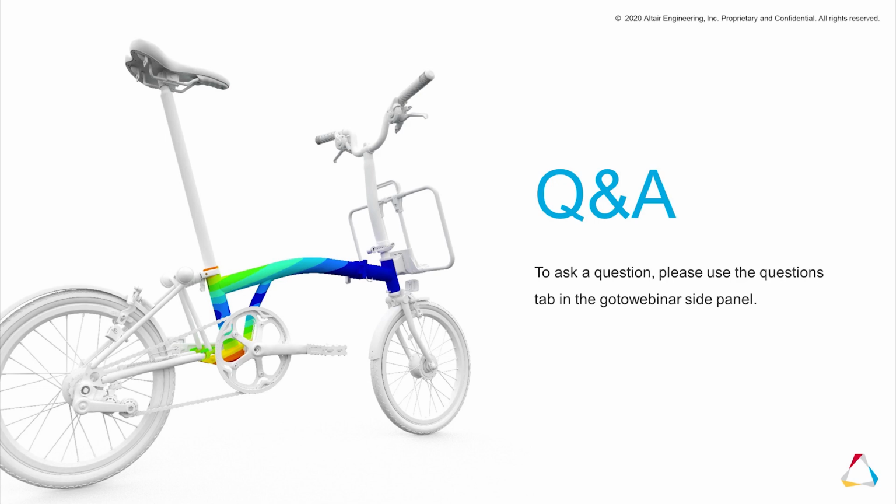Do the geometry import settings have a big influence on the results? In SimSolid, we bring in solids and the surface faces, but then we create facets on the face. The reason we bring in a faceted surface is efficiency. It makes it more lightweight than having to bring in a heavy surface and solid model. The rule of thumb is you just need the facets to be visually the same as what you'd expect. Of course, if you have 4 facets to define a cylinder, it's not going to be very accurate. But if you have an adequate number around the cylinder, it's fine. It will solve the facet geometry, though, so you need to be aware of that.